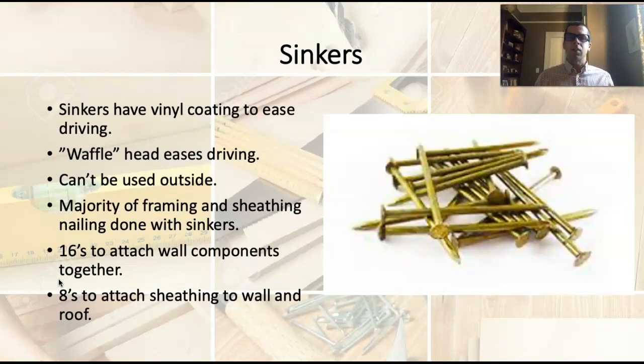Okay, we already kind of talked a little bit about sinkers, but they've got that vinyl coating that makes them easier to drive. They also have a waffle head on the end of the nail. Okay, they have this checkered, knurled pattern on the head of the nail that makes it easier for your hammer to grip the nail. It's less likely to slip off the nail as you're driving those nails in, okay? We can't use these outside. I've seen some really awful homeowner type work where they built fences or decks using sinkers and they just rust within days, especially around here. It's just wet all the time and you'll have these rust streaks all over everything, okay?